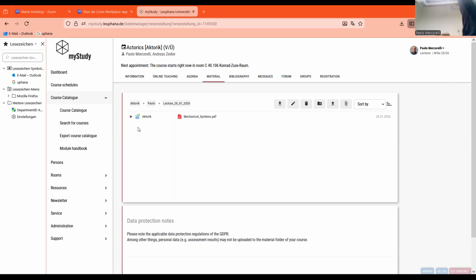This means you can think that this theta is not one angle, which I have just to describe the rotational movement of the rotor. If the mechanical system is complex, you have a vector. And this inertial matrix should consider all elements in the robot. Excuse me, this mimic, but just to understand why I put it here, because it could be really complex.